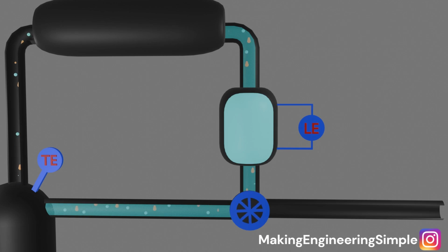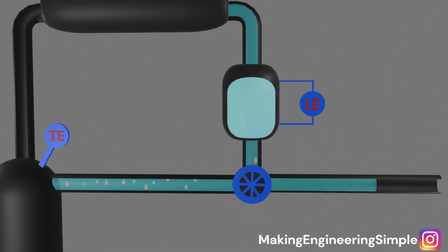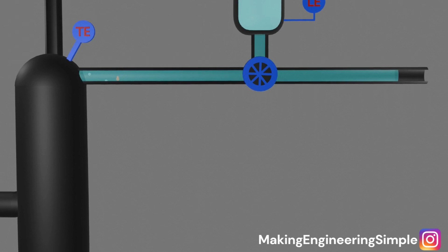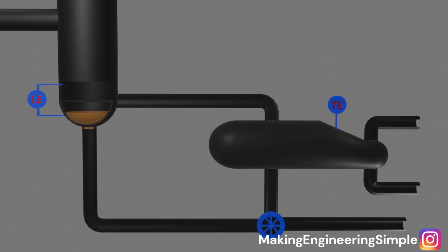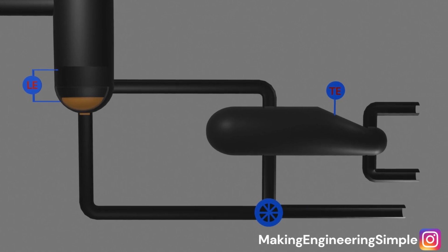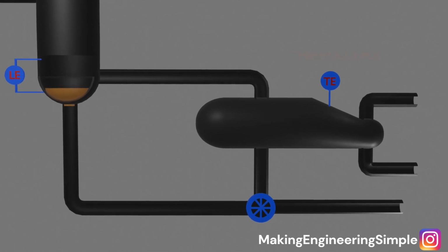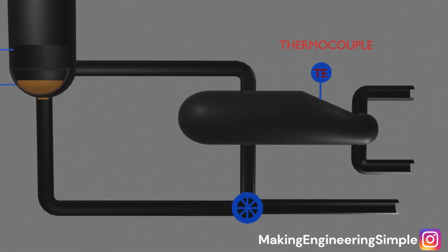Because our temperature control is already keeping the heavy molecules out, we know that as long as the temperature is correct, the liquid in this drum is guaranteed to be on spec. The bottom of the column operates on the exact same principles, just in reverse. It starts with the temperature trigger. A temperature sensor in the lower trays or the reboiler constantly measures the heat.